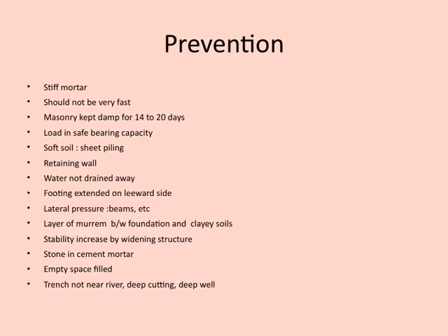When it comes to prevention, there are several key considerations to keep in mind. First, using stiff mortar is important, but it shouldn't be applied too quickly, as that can cause issues with bonding. After masonry work, it's essential to keep the structure damp for about 14 to 20 days to ensure proper curing and strength development. When loading a structure, always make sure it is within the safe bearing capacity to prevent settling or failure. In areas with soft soil, techniques like sheet piling can be used to provide additional support and stability.